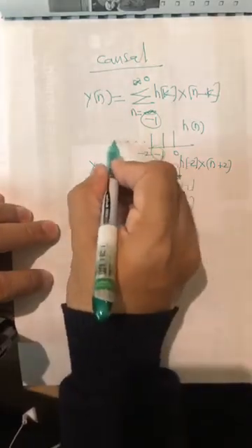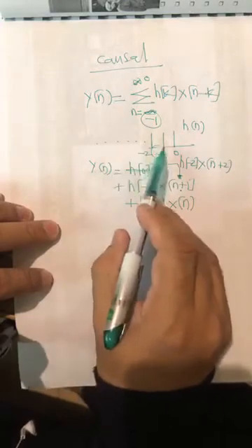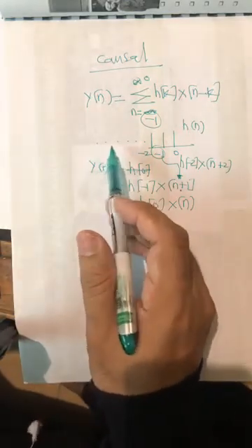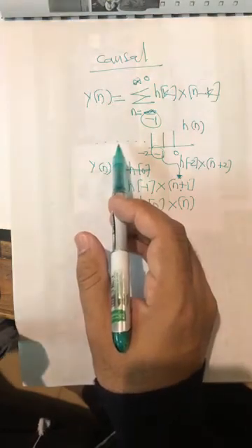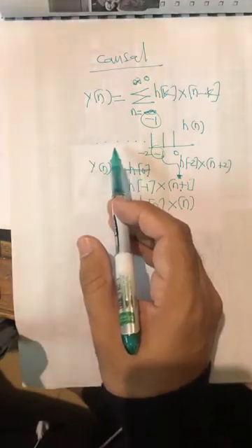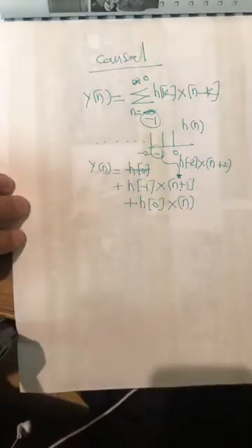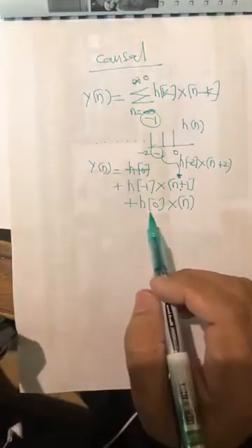As you move in the negative direction, your impulse response requires that many future samples, which you don't like, because future samples mean a delay. You have to wait for the future samples to be acquired, and only then can you do the processing. So in real-time signal processing, in 1D signal processing, you hate to use future samples in your computation.